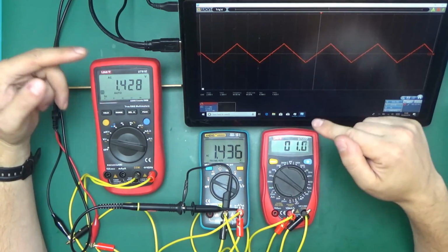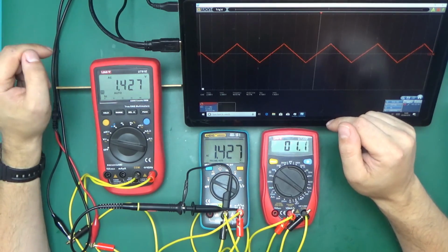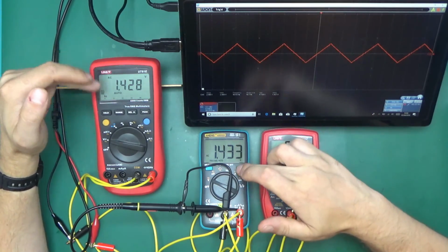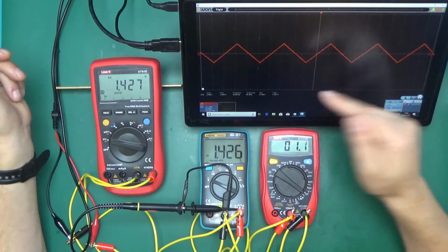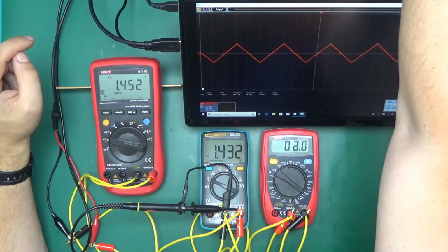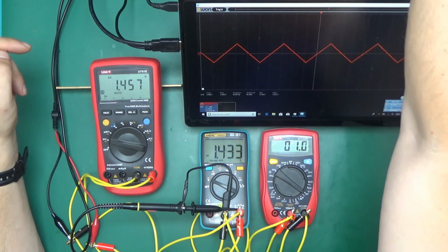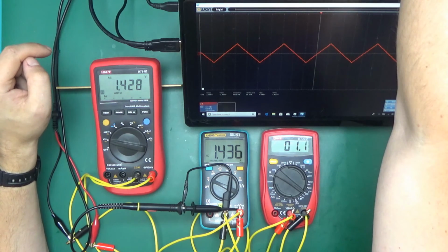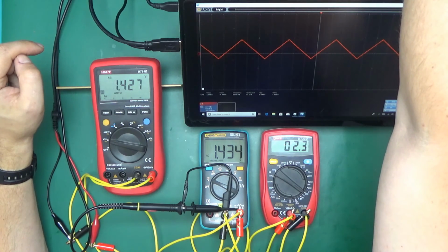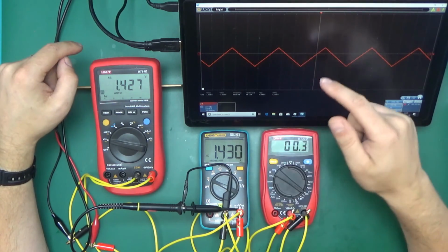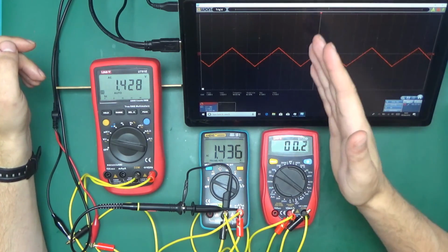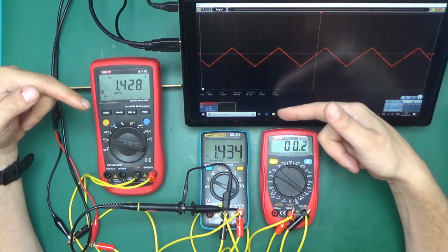Here is another example of a triangle wave, 50 Hz, 5 volts peak to peak, 5 volts amplitude, and the RMS value is 1.43 volts, which, this one is wrong as usual. Oscilloscope also shows 1.43. Applying any sort of offset to it, either positive or negative, makes no change over here. Interestingly, on the oscilloscope, it actually does make a difference. So if I go 1 volt extra, it will show me 1.83 RMS value, closer than those two, because applying a volt up or down over here would change slightly the RMS value of a square wave, because the edges are so sharp, so quickly changes from one state to another.